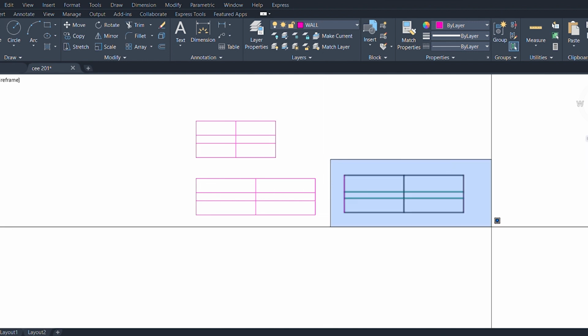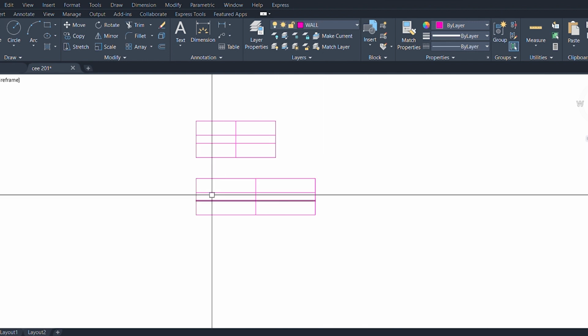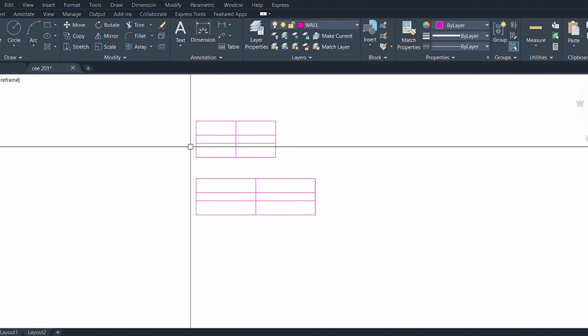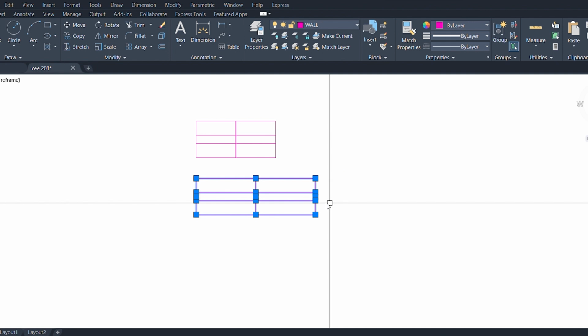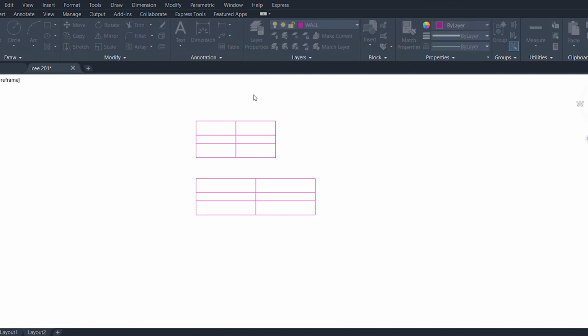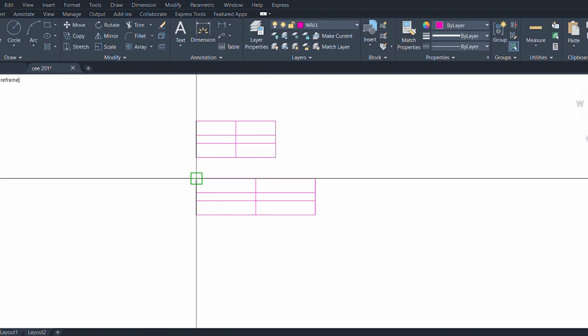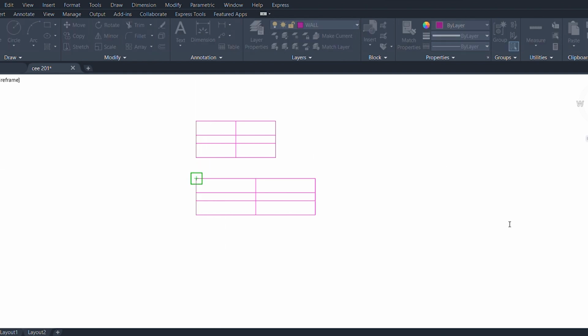From here now we can turn this one to a block. So to turn this one to a block now, you just press B and enter block. It will ask you to tell it the name of the block. So let's call this one W5, and we want to specify the base point. Yes, I'm going to make this point my base point. So allow explosion, yes, allow exploding, yes, that's nice. So I can press OK.